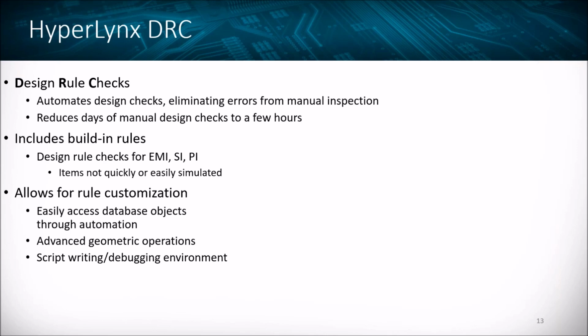Okay, and I do see one question from David. Can DRC use both TCE or ODB++? And that is correct. So the best way to bring in a design file from any CAD tool into HyperLynx DRC would be ODB++, but it also can use TCE directly from Expedition or PADS Professional Layout.